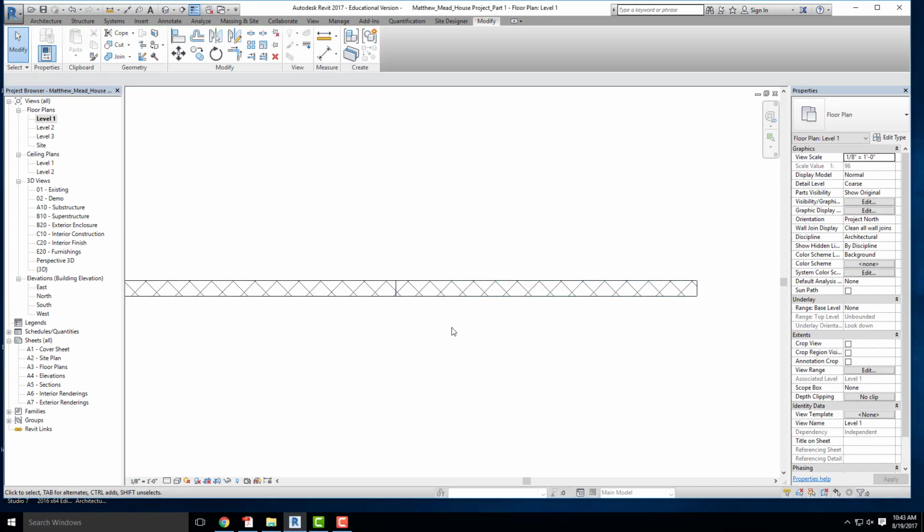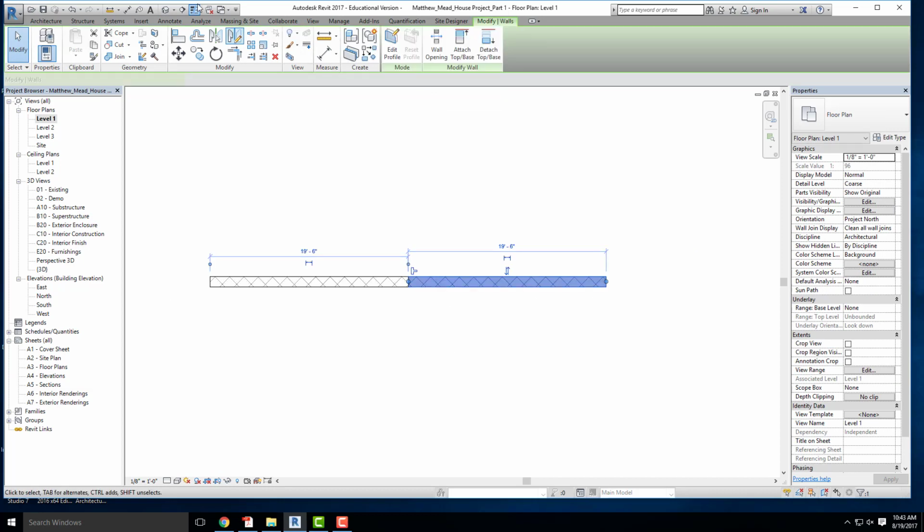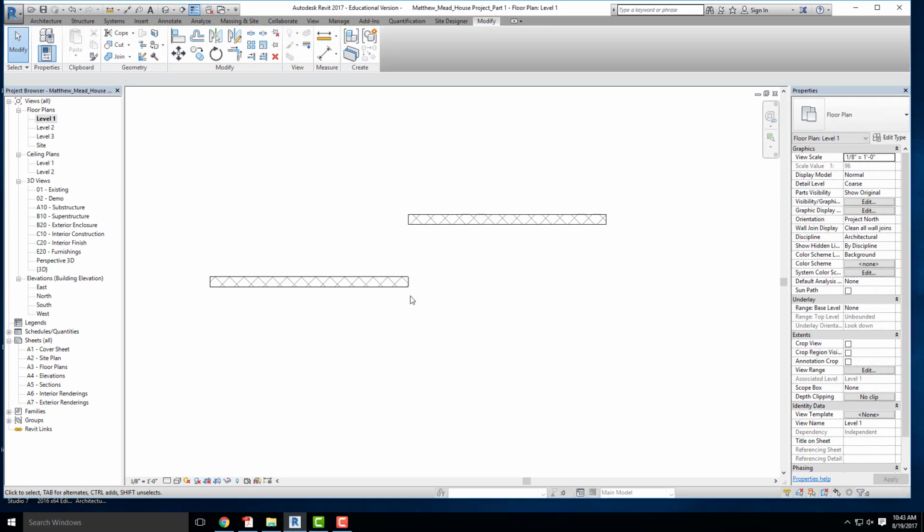In plan view, that's going to look exactly the same, but if I try to actually manipulate that wall now, so I try to now move it up, they're not joined together, so it'll actually allow me to split those walls apart without them moving with each other. So you will run into that situation, likely today, when you want to move a wall, but maybe those 2 walls are already joined. That's how you can prevent them from moving with each other.